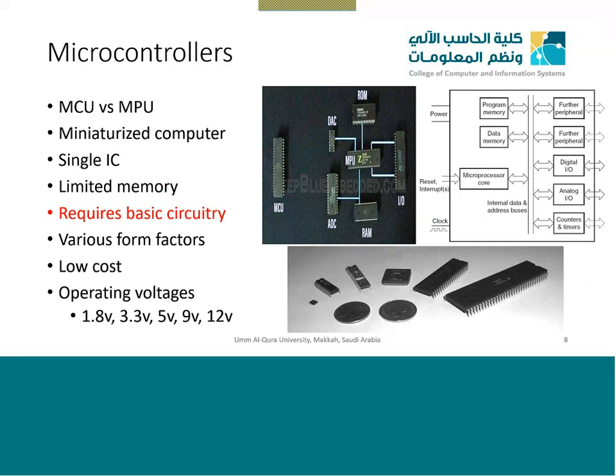The difference between a microprocessor and a microcontroller is that in the black image on your right side is the microprocessor, and on the left is a microcontroller. A microcontroller is a simplified microprocessor together with the RAM, ROM, input and output ports and everything in a single IC. It is just like your Intel Core i7 or Core i5, but for those microprocessors to run, you need a motherboard, some RAM, some ROM.